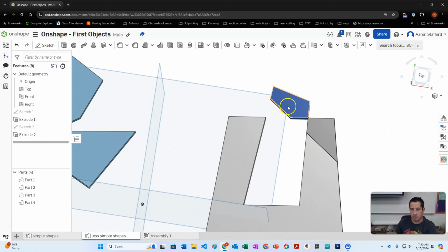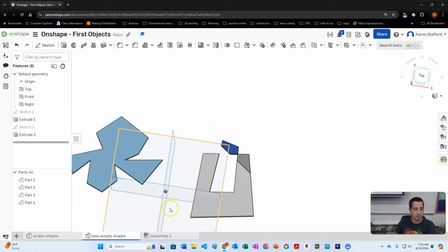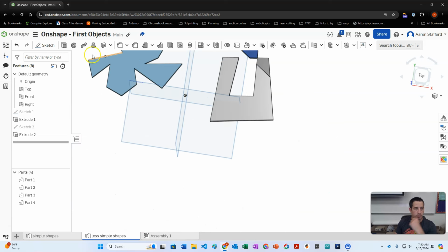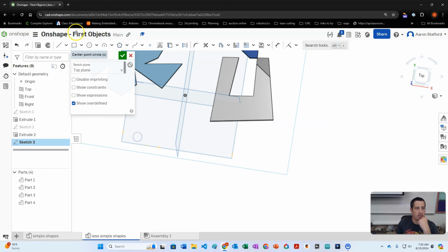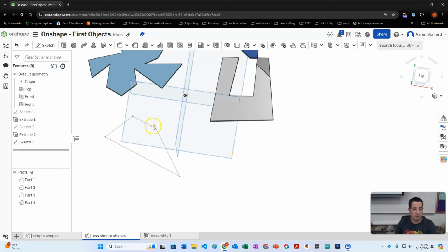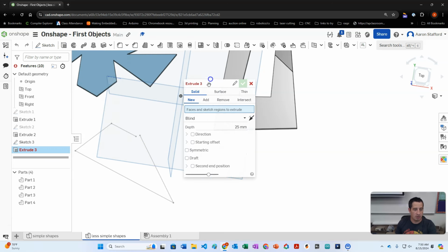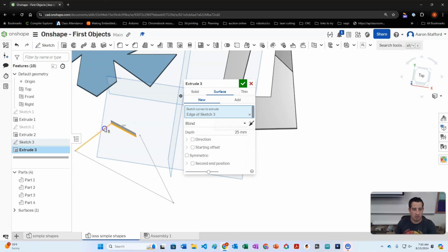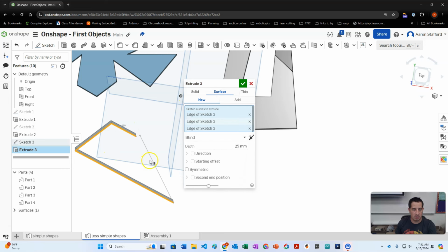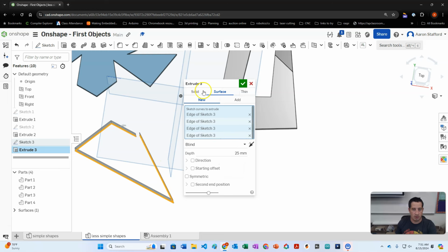And look, these ones are detached from each other. They're all different shapes. And so what happened here was when I extruded it, I created 3 separate things. There's one more thing I want to show here. If I try to sketch something, and you can see here that, escape, that this one never turned gray, right? And so if I extrude it, it's not going to let me select this region, okay? I can select it and extrude the surfaces, but this is not something we're doing right now.